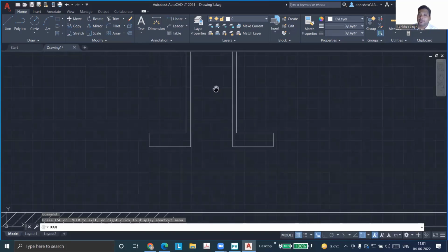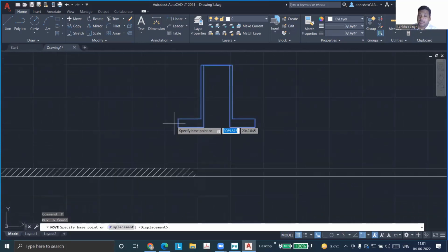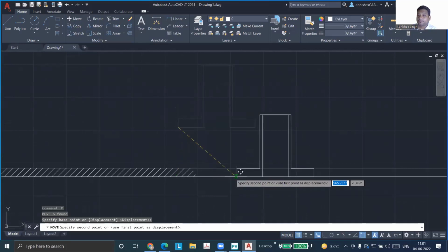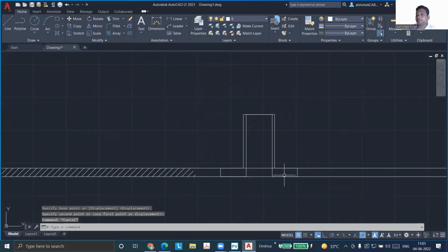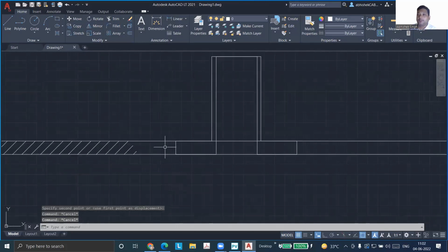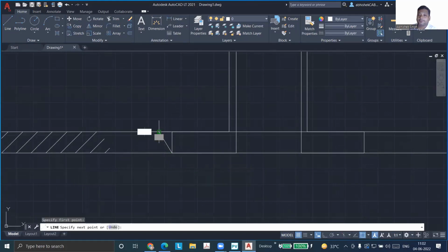Now if I have to weld this nozzle, I'll bring it down to that. I'll have to make an opening from here. Now it will be attached here and you can provide a WEP like this, and do a complete full penetration weld with radiography possible. So this is when your nozzle welds are getting radiographed.